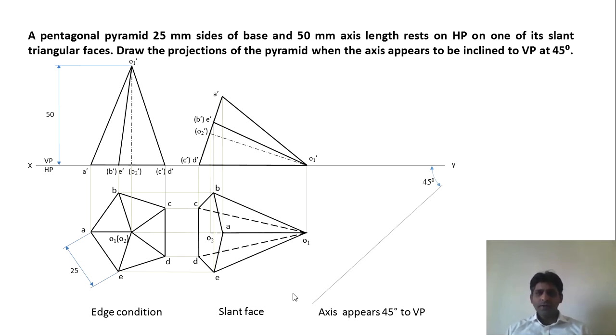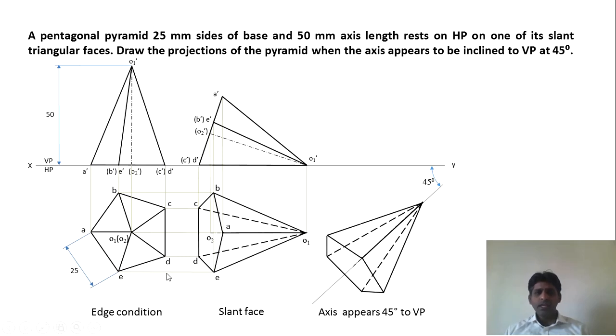So draw a line at 45 degrees and reconstruct this. Reconstruction I have explained in the previous videos. Mark point O1, mark this point O1 and measure O2 and mark this point O2 by drawing an arc using compass. And with respect to these points, you can get all other points. So O1B, you measure O1B and mark here. At the same time, you can mark O1E also. Then O2B, you measure O2B using a compass, and from here you mark O2B, and at the same time you can mark this point also.